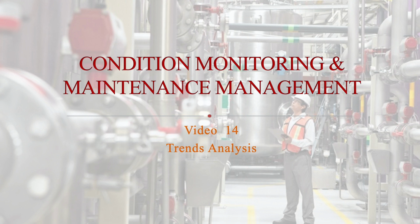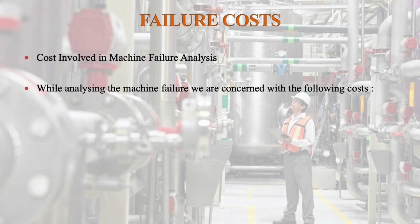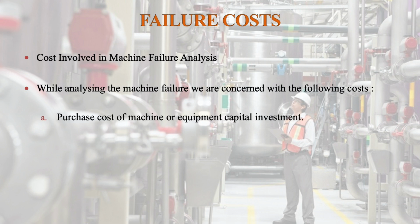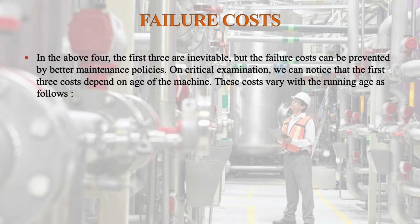In the last video we talked about failure rates, but here we will talk about failure costs, the costs involved in machine failure analysis. While analyzing machine failure, we are concerned with the following costs: purchase cost of the machine or equipment (capital investment), depreciation or salvage value or scrap value, running costs including maintenance, repair and operating costs, failure costs and damage costs. Of these four, the first three are inevitable, but the failure costs can be prevented by better maintenance policies.